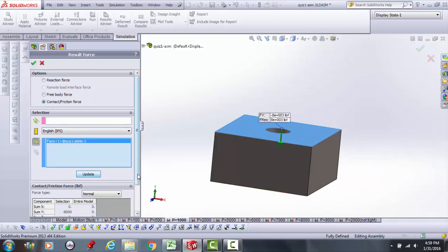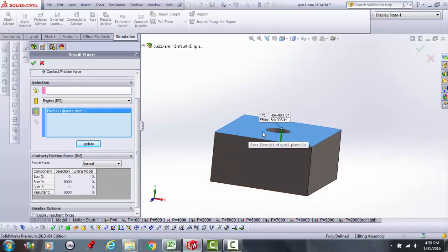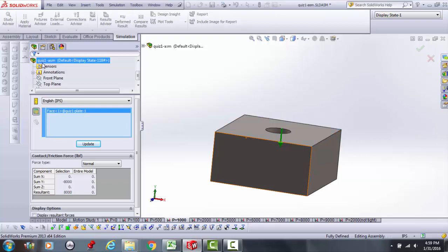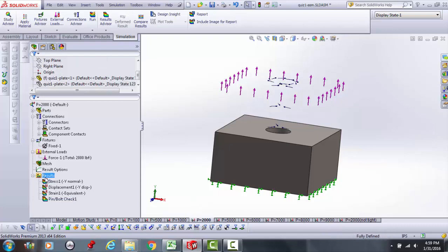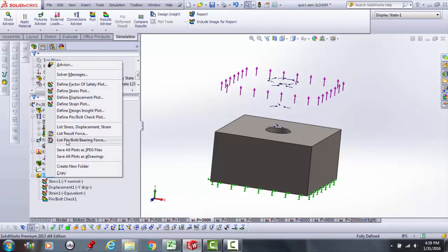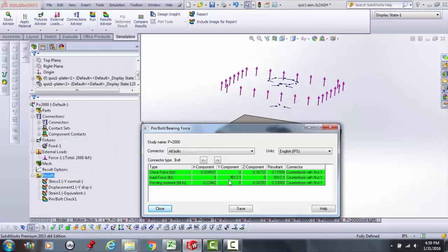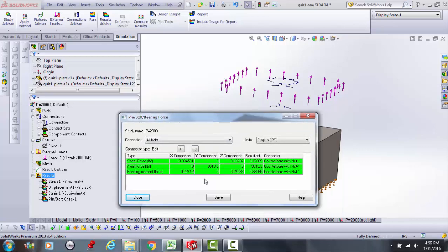Contact, boom. So it's put all of that 1,000 pounds on the members. It's not right. Let's go up to 2,000 pounds. We'll start bearing our bolt force. Again, it's starting to accumulate a little bit, but it's basically still 9,000. It should be 9,000 plus 17% of 2,000.